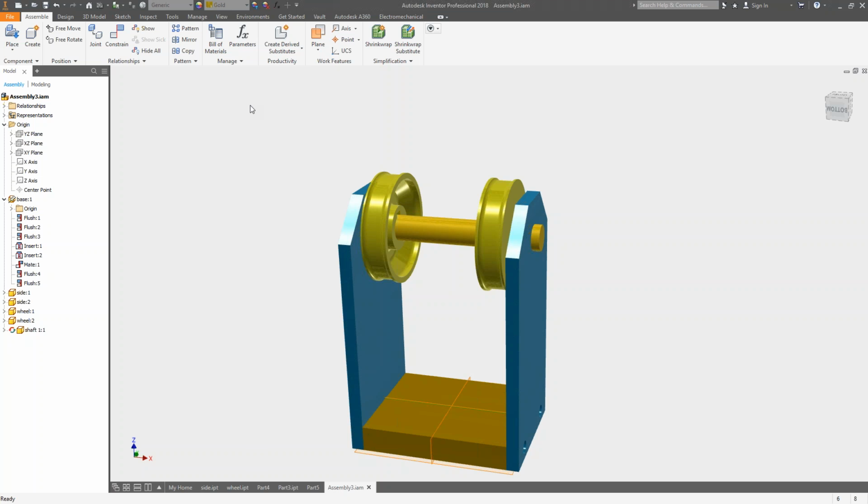You don't just want to make absolutely everything in your assembly adaptive, because when those changes start to propagate, it could cause problems, right? So let's say this shaft was a common component that is that particular size. If I make this adaptive and then I change the length and width of this and it automatically updates, well, what if that shaft is used somewhere else?